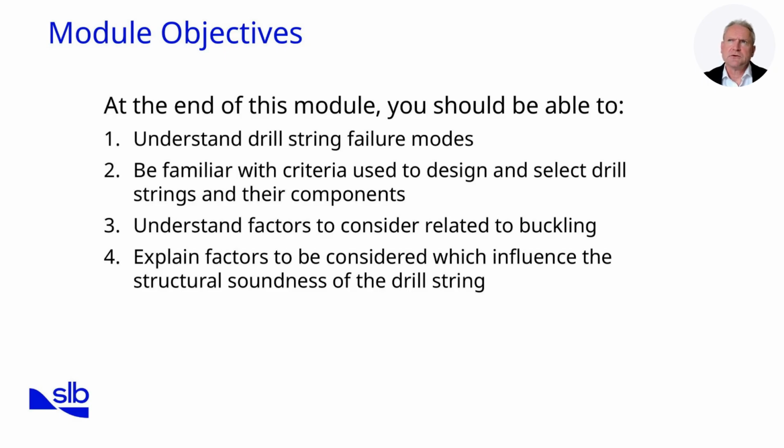Next, we will review factors that influence buckling, including axial load, well inclination, pipe stiffness, and borehole clearance. We will then explore the Dawson-Pasley formula for critical buckling load, which gives us a practical method to evaluate when drill string buckling is likely to occur. Building on this, we will consider common field practices and tips to prevent or control buckling during drilling.